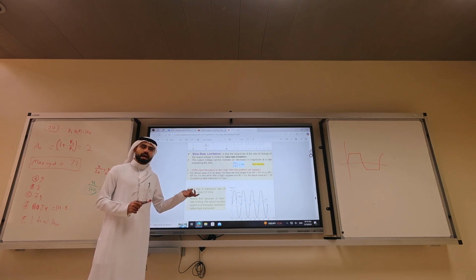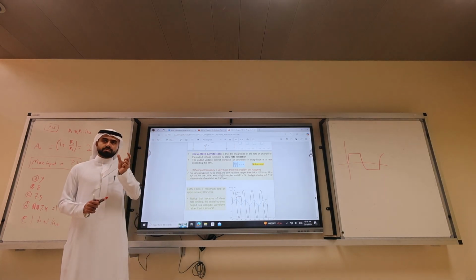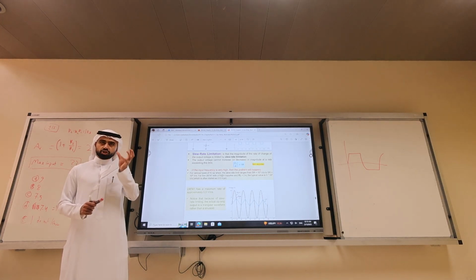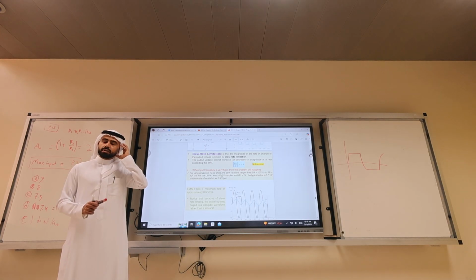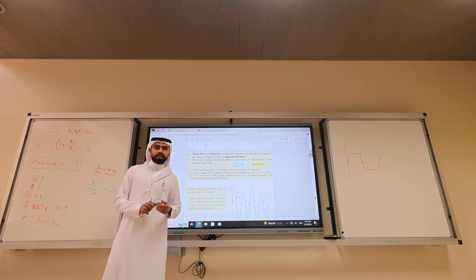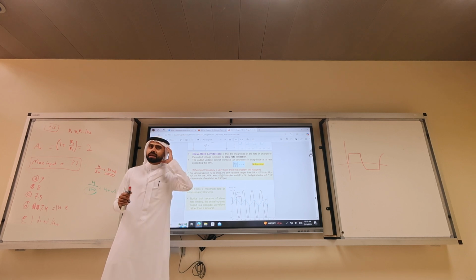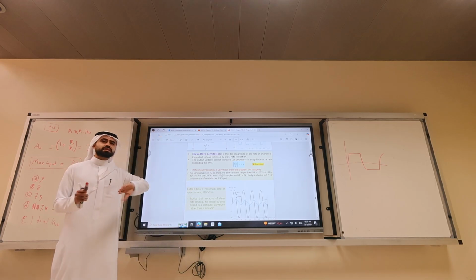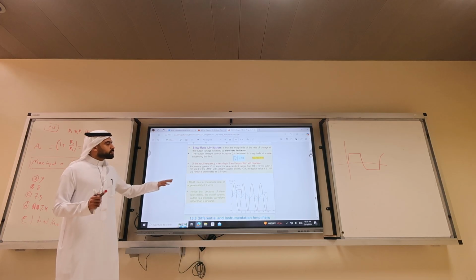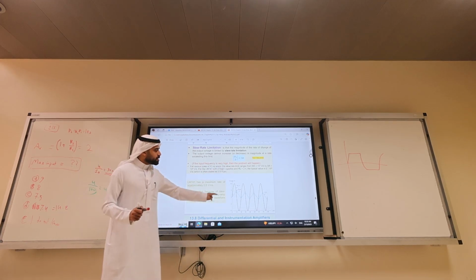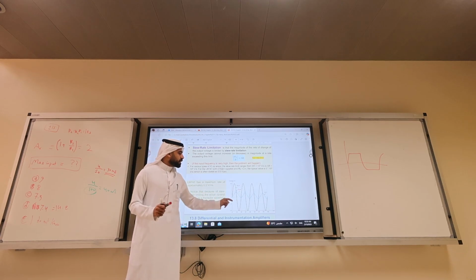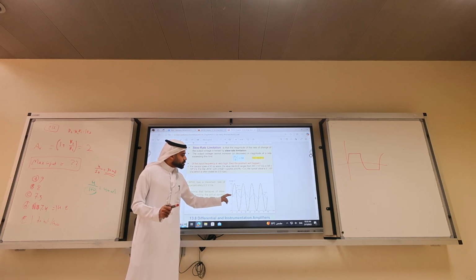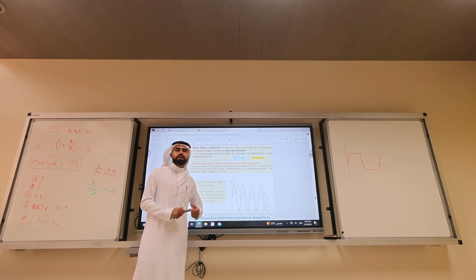frequency, for example, there are certain spectrums in the music that with cheap headphones you cannot hear, but with expensive headphones you can hear. Get it? Sometimes if you play some music, cheap headphones would clip and would not give you enough quality of the signal. It will eliminate certain frequencies. This has to do with what we call the change of the voltage as a function of time. So if the input is sinusoidal, that changes very quickly. Sometimes the op-amp cannot catch up. The rate is smaller, so you will have triangular shapes rather than sinusoidal shapes.